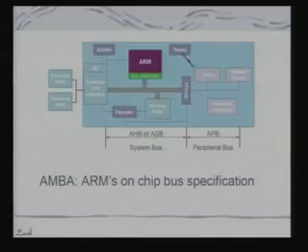So you go back to the picture that we had already seen earlier. You have this ARM processor, it has its bus interface, making the interface compatible with what is called the AMBA bus. Now obviously when I have a bus and a definition of the signals, they may not always be the same as the signals provided by the processor core.